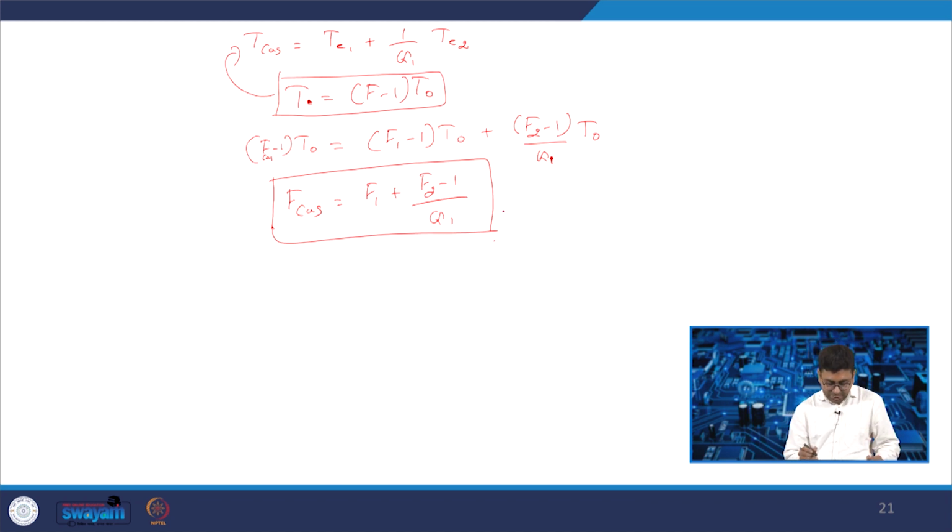If I elaborate, F cascaded equals F1 plus F2 minus 1 by G1 plus F3 minus 1 by G1 G2, and it will go on.